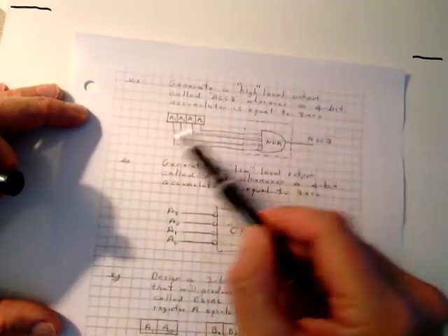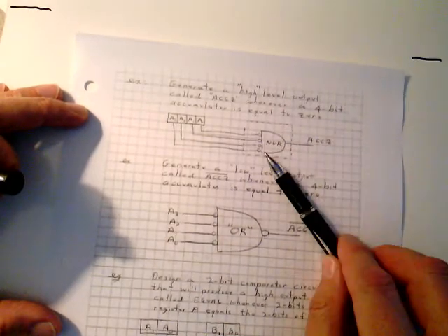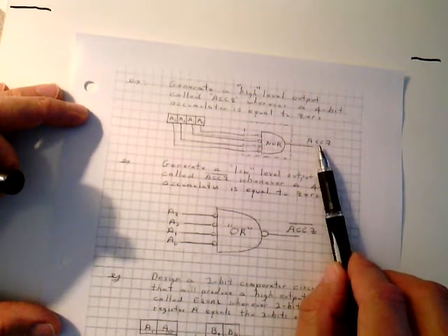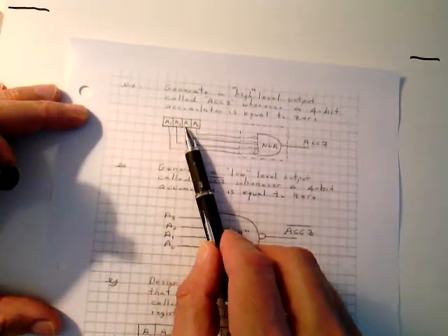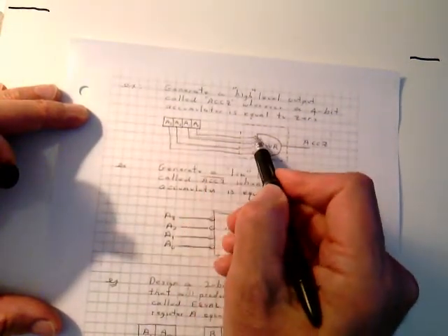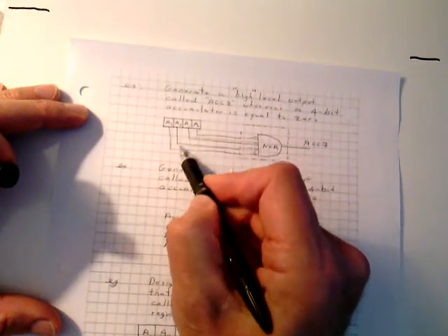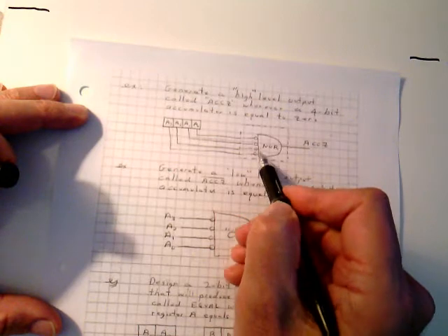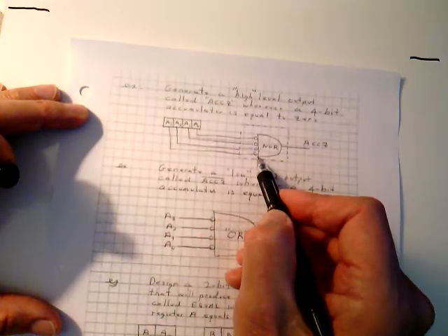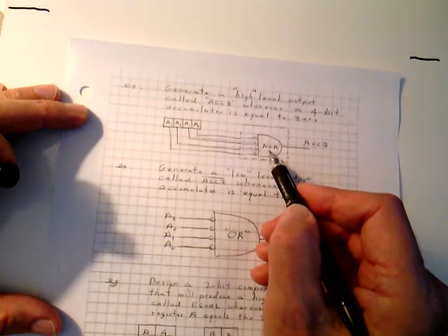You can use a truth table and go through it, but sometimes it's just think of what you need. Remember the previous page. We want to generate an output called accumulator 0 whenever all of those bits are 0. That's going to go high. Well, look, when this is low, and this is low, and this is low, low active, and, I'm saying and, every time, it's an AND gate, this is low. I want the output to go high. You draw the story and you look at it and say, well, that's a NOR gate.